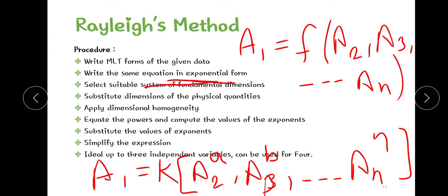Okay, after the solution, the values of a, b, c and so on are found out, and these values are substituted in the main equation. After simplification it yields dimensionless groups controlling the phenomena, and after the procedure we will get the dimensionless number.